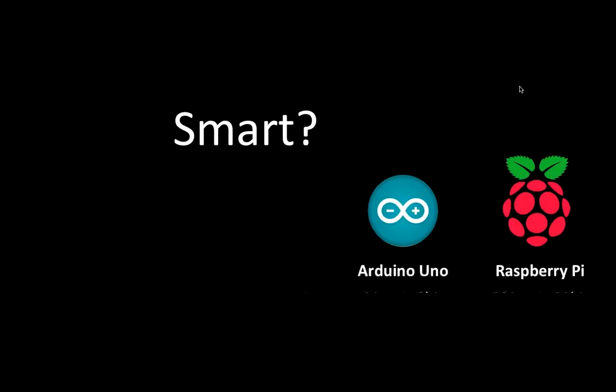Well, let's take a look at two of the maybe most popular ones. So we have the Arduino Uno board, which is the most common Arduino board currently. It's not actually a computer. It's considered a microcontroller. So when you look at the hardware specifications of a typical Arduino board like the Uno, you can see that it only has a 20 megahertz CPU, which is 8 bits, not gigahertzes, megahertzes, only a couple of kilobytes of memory and storage. So it's not really a powerful computer.